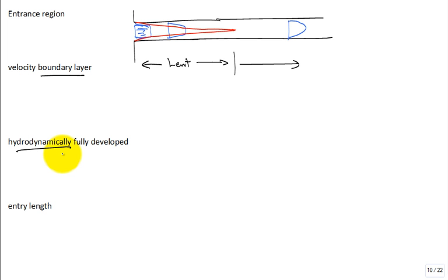This course is a prerequisite to another course called heat transfer. You could have a cold fluid with hot walls, and you would have to be thermally becoming fully developed, where you get a temperature profile in the pipe. So that's why here, hydrodynamically, is the velocity profile fully developed. Later, next class, is it thermally fully developed? And different parameters, the Prandtl number, will tell you, does it develop quicker thermally or slower thermally? If the Prandtl number is around 1, they develop at the same rate.